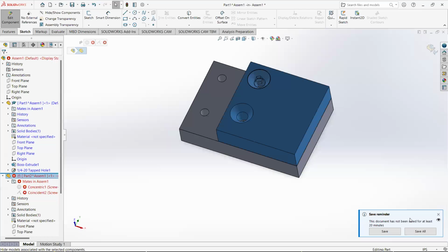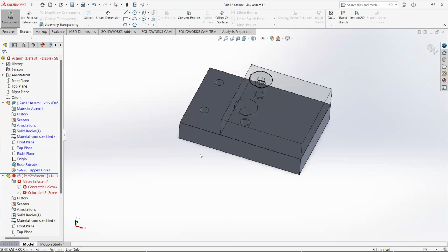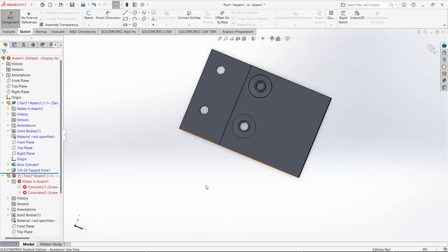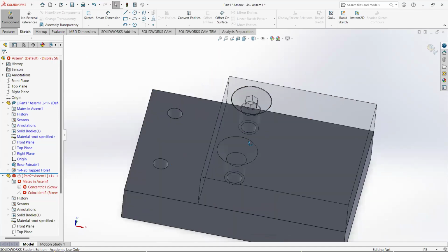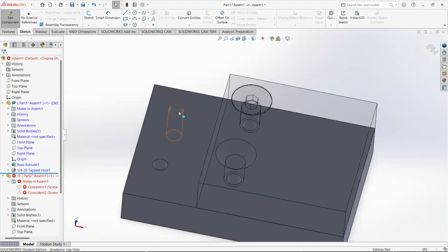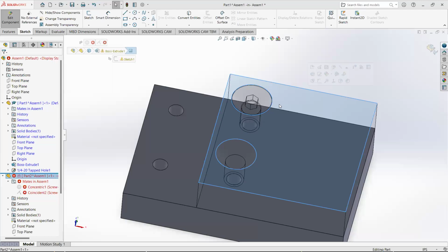And you're sort of real time, as I record this, stream of consciousness, encountering one of the other problems that can pop up with a lot of in-context assemblies. The countersunk holes, right now, there's only 2 of them because they were constrained. 2 of them were constrained to this hole and this hole. The problem was SolidWorks is trying to make them exist. They're trying to make 2 holes here, except there's no material, right? Our top plate stops short.